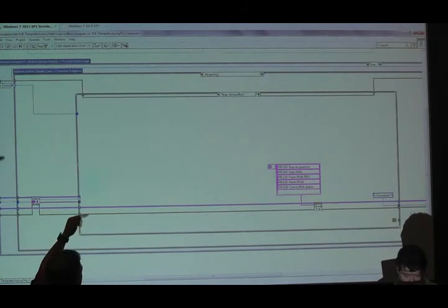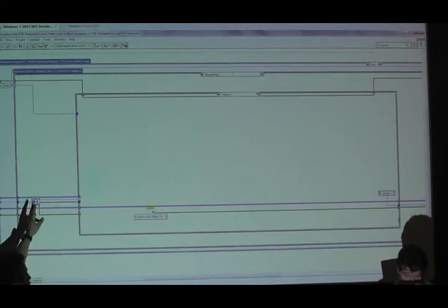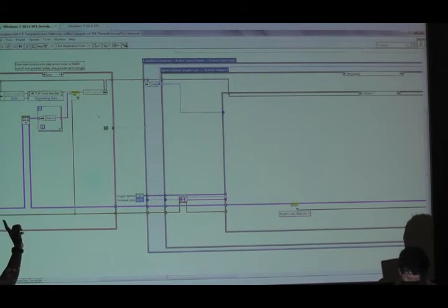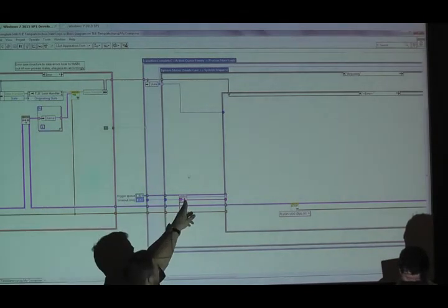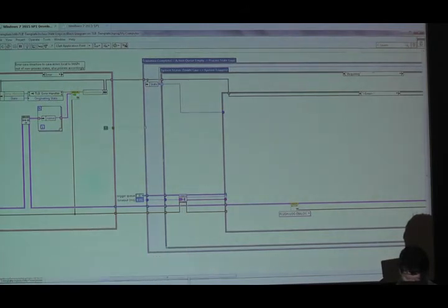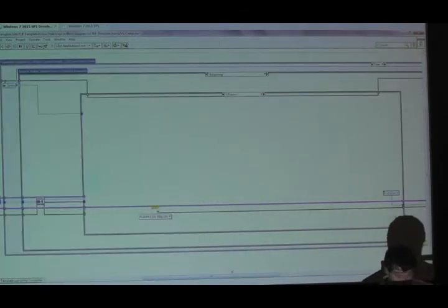So out of acquiring, if I'm in the acquiring state and an error has happened, what ends up happening is a trigger gets enqueued at the front that you haven't seen. That happens in that other case structure up immediately before this. So an error trigger, per se, makes its way onto this trigger queue, and so now the way that you think about how to handle your error is, I'm in this state, I've gotten an error, here's my information, what do I do?